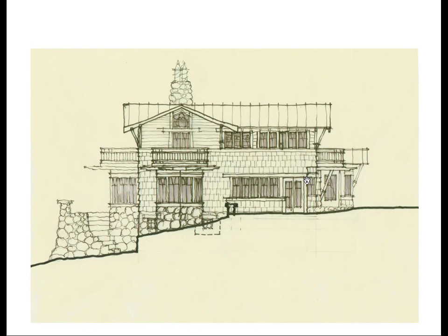But if we continue on the line weight thing, notice that when we talked about floor plans last class, we talked about how we were cutting through the walls. Well, we're not doing that here, so we have to think about it a little bit differently. Typically your biggest line weight, as I just mentioned, is the ground plane, which would be the thickest. The next thickest is going to be the next closest thing in the elevation. So when you're drawing your building or your house today, think about all the different planes that you might have: what is the closest? In this example, this is going to be the closest right here.